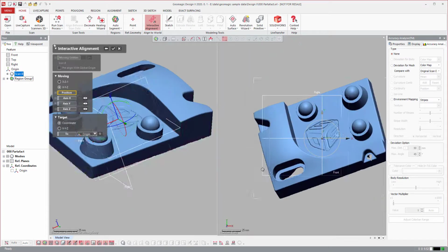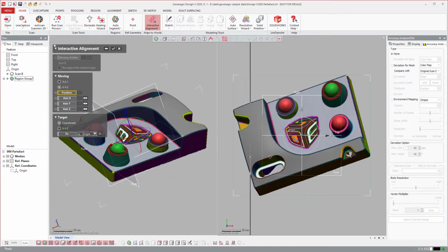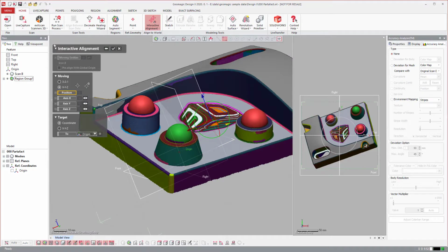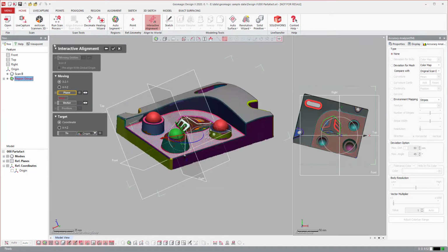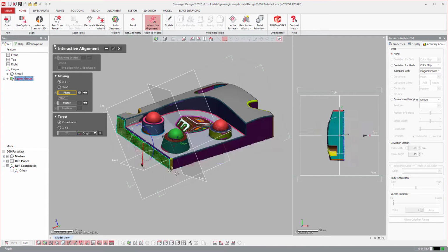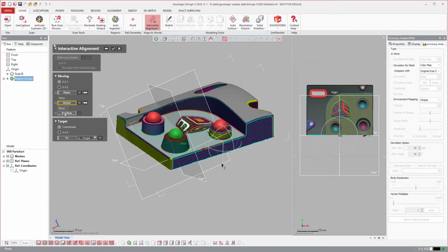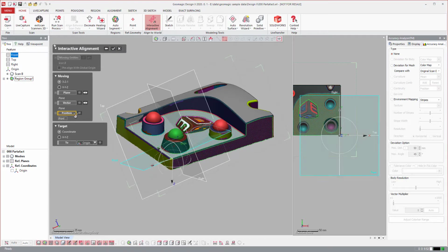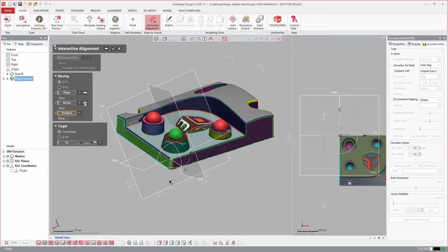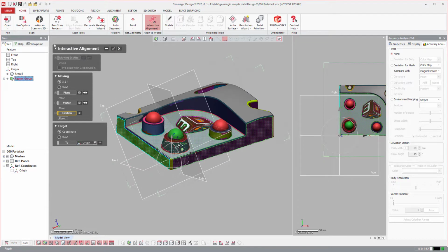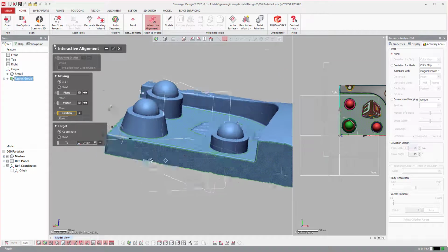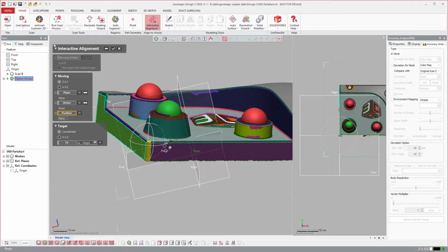There are a whole host of ways to align parts to the world coordinate system, but the most simple way is to do what we call a 3-2-1 alignment, where you can select a plane, and a plane. If I'm going to select the top plane here, select the side plane as my vector, and select this plane here, and I accidentally clicked on the side there. Then if I need to flip-flop my coordinate system, I can do so, or I can flip-flop the orientation. And you see it puts my coordinate system right there on the edge.